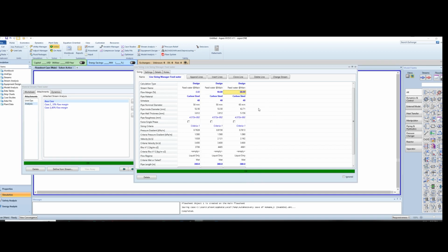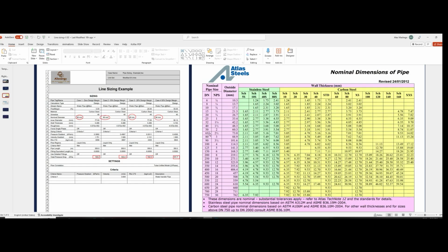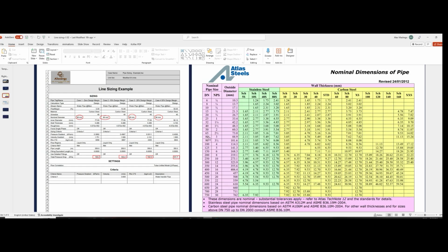But a tip, in practice, a 2.5 inch line is not really common. Yeah, it is a standard pipe size, as you can see from the tables here. It's a standard pipe, but you don't really necessarily find it off the shelf that easily. And what makes it even more complicated is if you were to put valves and other fittings, it will be very hard to find a valve that is a 2.5 inch from my experience. So what I normally do, I'll go to the next size up, which is a 3 inch, which is common. Most of the valves and fittings will be off the shelf.